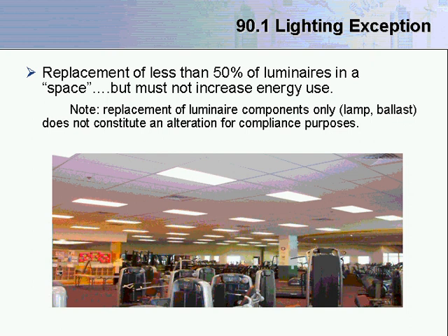And another note, just for clarification, if you're replacing, for example, all the ballasts in your building, or all the lamps and ballasts, but the fixtures remain the same, that is not considered an alteration or a renovation. That's more on the line of a repair, and therefore no compliance is required in that case. That covers the exemptions, so I'd like to pass it back over to Pam, and she's going to show you how this all works in the software.